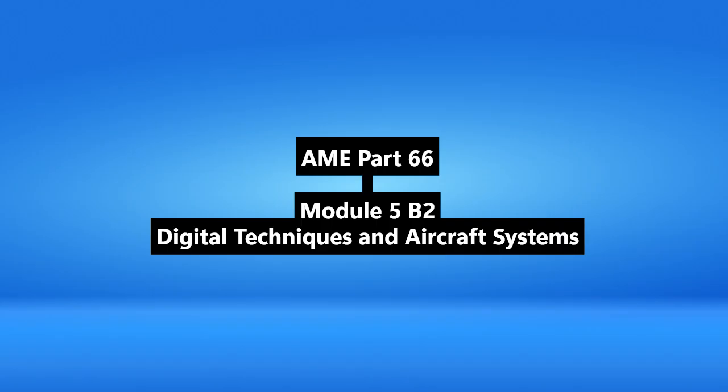And I guess the place to start is the absolute basics, the language these systems use, and how they translate things from our analog world, numbering systems and data conversion. Absolutely fundamental. You really can't get away from binary. It's the native language, machine language, just zeros and ones, base 2. And each position, moving right to left, is a power of 2. So like the binary number 0011, that's, let's say, 1 times 2 to the 0 plus 1 times 2 to the 1, which just gives you 3 in decimal. Pretty simple concept at its core.